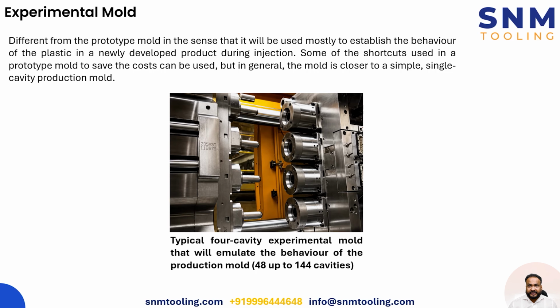The cycle time during the start of production and at the time when production is repetitive and more or less autonomous, in simple words, if the product is getting produced repetitively with the best possible quality, to reach that level, an optimum cycle time needs to be set, and that can only be done while experimenting through an experimental mold.